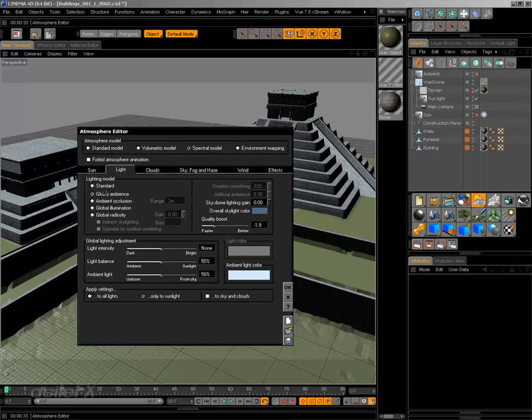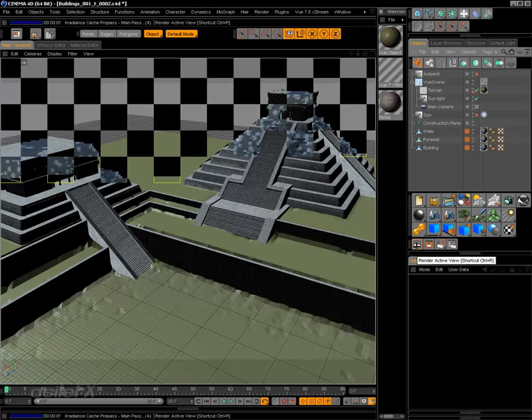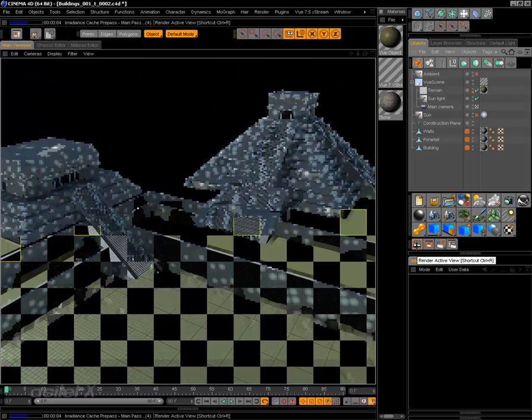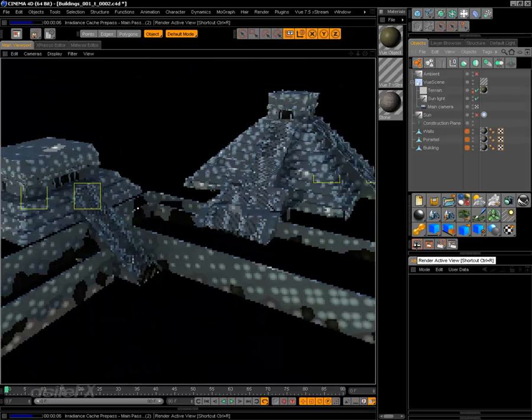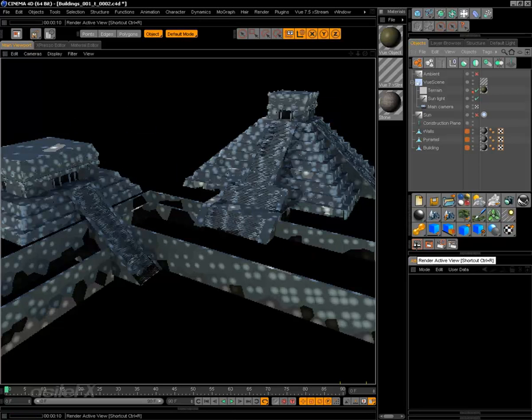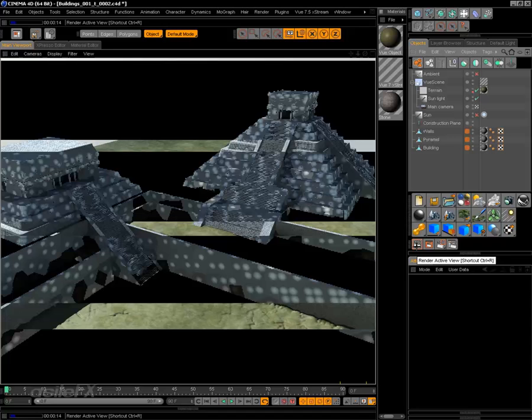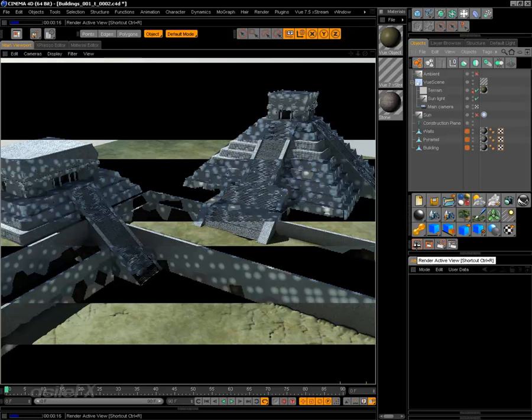So we can go in and turn that off, use the global ambience mode to still keep the lighting correct on the ground. And we're going to see pretty much the same result, except it is going to render quicker because we don't need to calculate the view pre-pass. So even with the low calculation I have set up for the GI in cinema, it still looks pretty good.